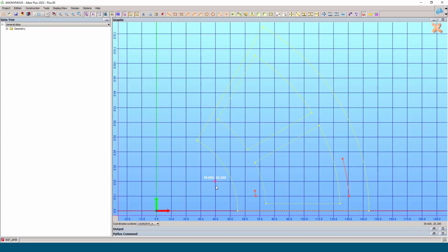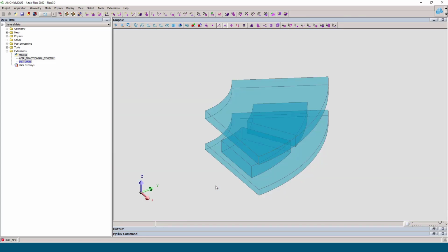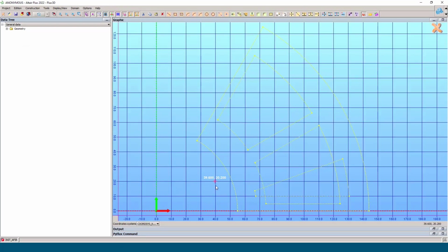Once the rotating part is complete, the macro starts to create the teeth, 3 in our case. To continue, the stator yoke is extruded and the bases of the teeth are built in 2D before creating the slots.